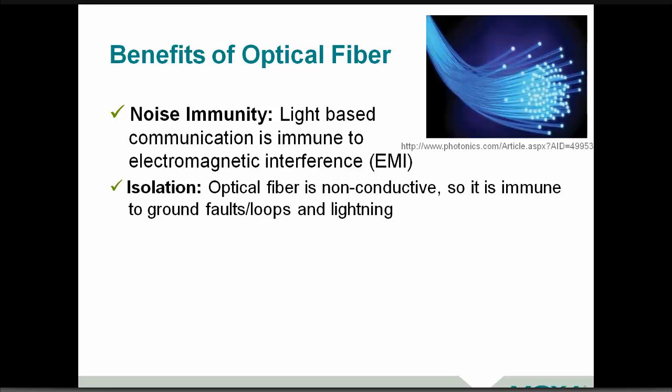Isolation. We're not dealing with electrical signals, so you can have different pieces of equipment at either end of the fiber, powered by different sources and at thousands of volts at different potential relative to ground. It doesn't matter because you have total optical isolation.